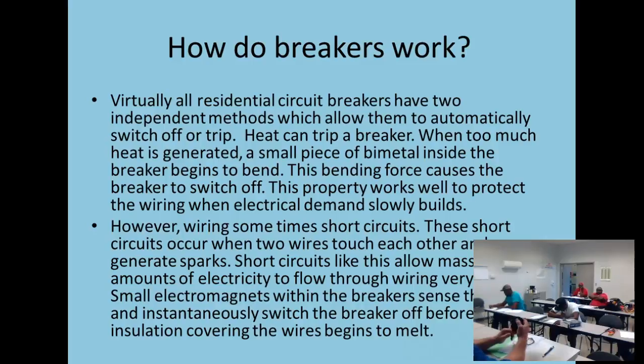Now, how would you test this? Well, the first test of this breaker would be, does it have power going into it, right? So I'm just going to test coming across it with my voltmeter, right? All right. Do I have voltage coming out of it? I do. Time to move on down the line. It's good.